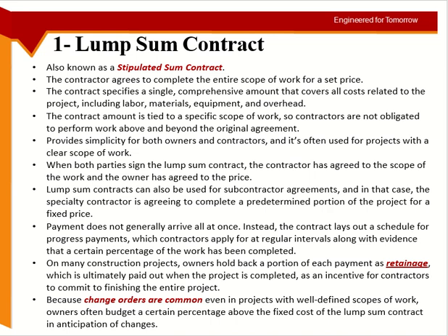So the whole project will cost you this much. Total lump sum means each item is not defined specifically. The total cost is given based upon the type of project you have. The contractor will give the total amount to the employer, to the client, for the whole project. It's a single cost, and that cost is supposed to cover everything, including labor, material, equipment, overheads.